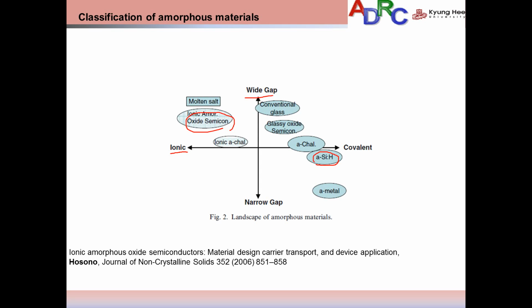These oxide semiconductors can have very high mobility, and also they have some stability and very good performances. Amorphous silicon has been used, as you may know, for TFTs for the past years, and the oxide semiconductors have been introduced by the year 2003 with indium gallium zinc oxide, that I will talk about a little bit just after.